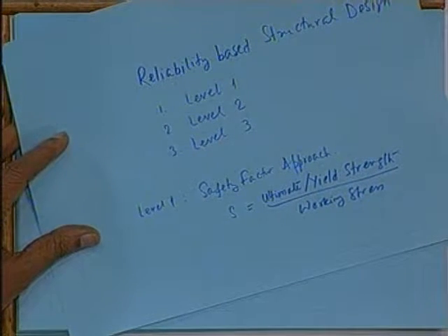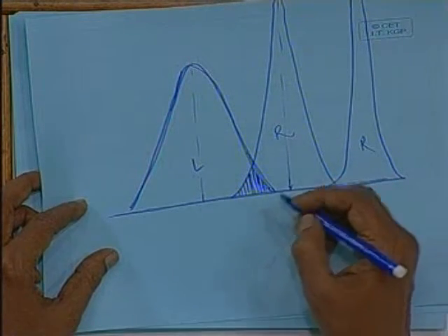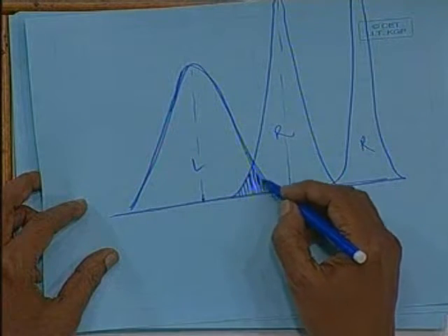Isn't it? So this is the safety factor approach which we normally use in standard structural design, including ships. All classification societies have a safety factor for all their formulations varying between 1 to 5. But this approach takes two values, one value of load, one value of resistance. It does not take this into account at all.